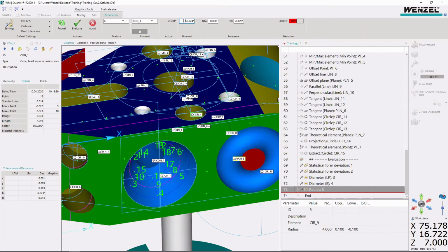And then maybe you think that this is not 59.72 something, you can change it, as long as this is valid for you. If it is like this in the actual format, then it cannot be changed. And then just key in your upper and lower tolerance as per normal, and then you will get the deviations. That's it.